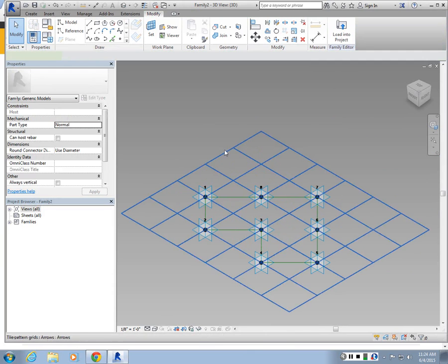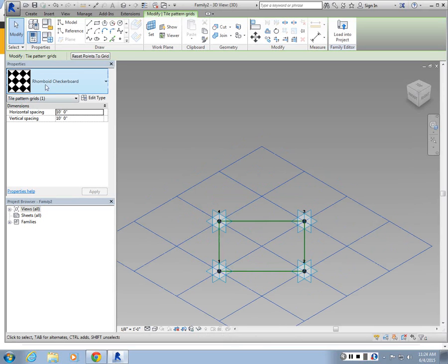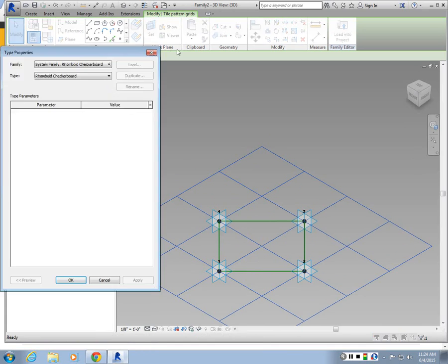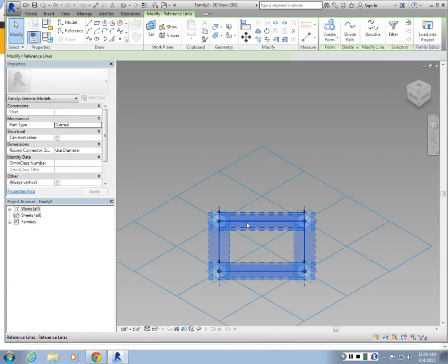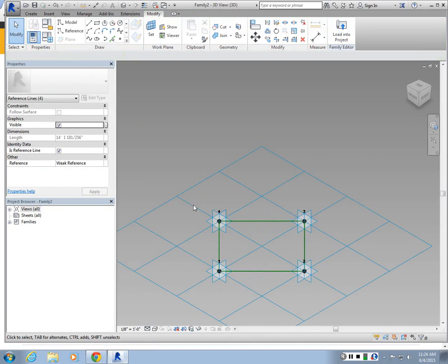Okay, so I haven't worked with these a lot. I would say these are already built in as voids. They're not solid. I don't see a built-in parameter for it. There's a visibility parameter, of course, but you could do it per panel if you want. If you make an instance parameter, you'll be able to choose individual panels and make them disappear. Is that what you're asking?